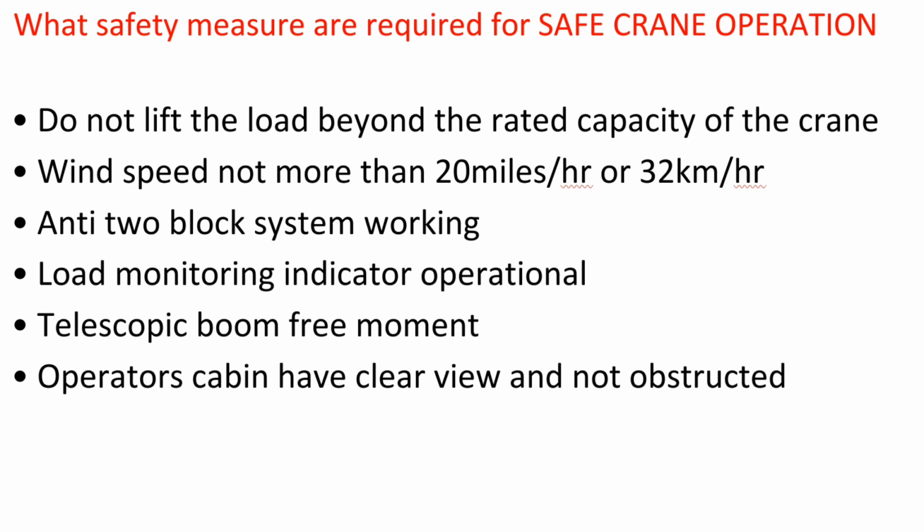Do not lift the load beyond the rated capacity of the crane. Wind speed not more than 20 miles per hour or 32 kilometers per hour. Anti-two-block system working. Load monitoring indicator operational. Telescopic boom free movement. Operator's cabin has a clear view and is not obstructed.